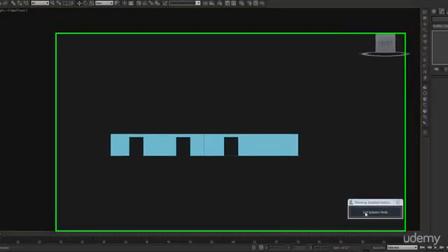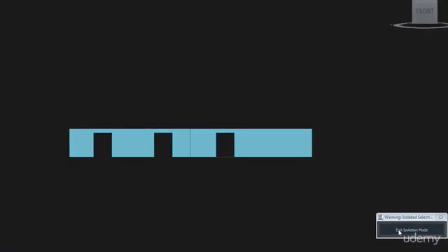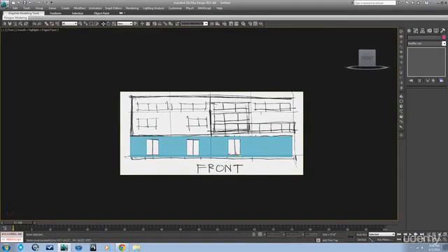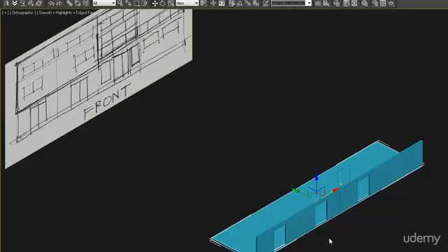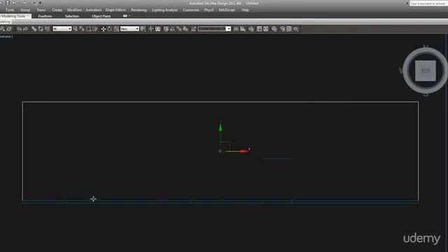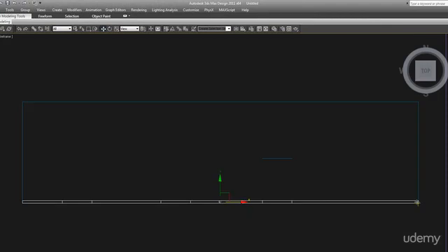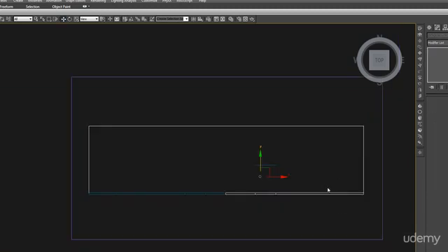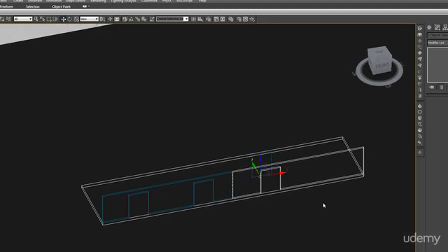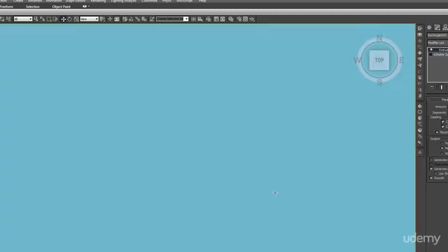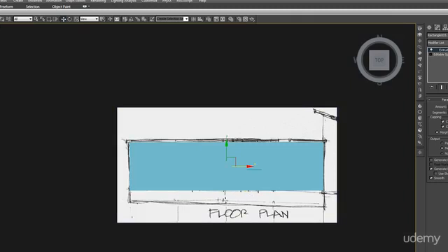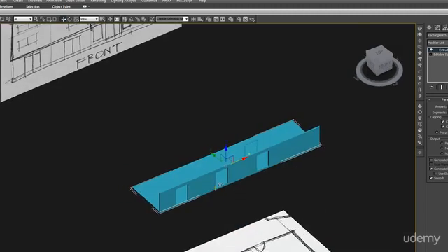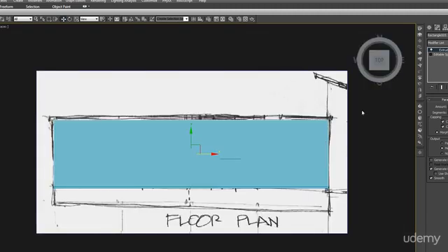Let me show you now the trick for doing the doors, for example. We've seen how to make simple walls. We have our floor plate here, and we need to move our walls back 6 inches. Just like that. Okay. So now we're good. We've got our floor. On the bottom floor, we want it to come all the way out for this deck that we have out here. So let's extend that out. Our walls are already in the right place.